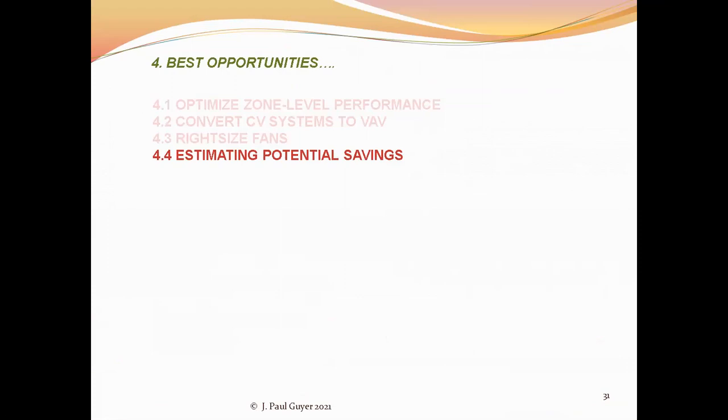In constant volume systems, diagnosing an oversized fan. If it is not economically feasible to retrofit the constant volume system to a VAV system, then right sizing the constant volume system fan is generally a profitable choice.